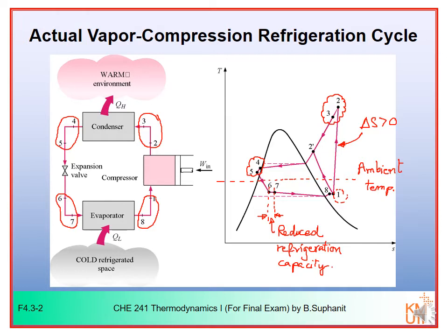On the other hand, if the heat transfer to the surroundings dominates the process, the compression process will follow path 1 2 prime instead. So in this case, you can see that in path 1 2 prime, you have a decrease in entropy with the heat transfer effect.